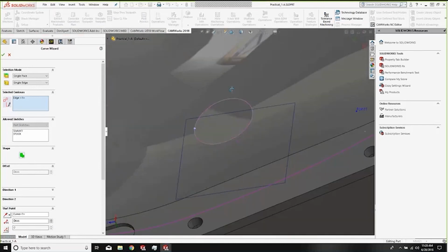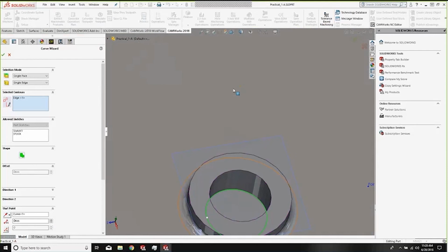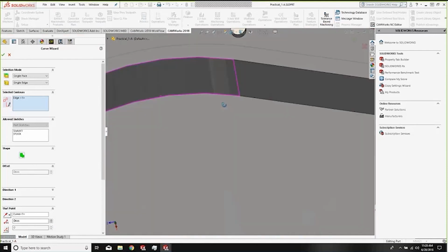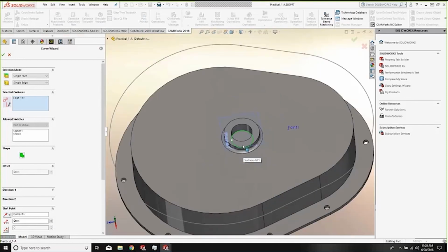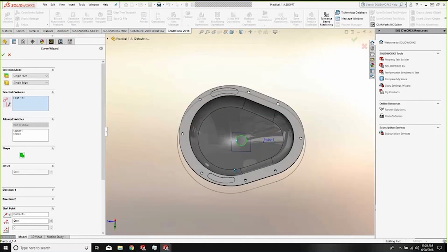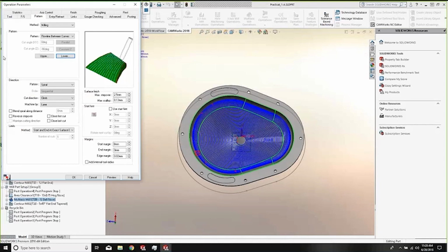This chain right here, which is actually a hole that gets punched through there. Now, the reason I can select that is because I drilled a hole from this side. So there's not going to be any material there. So that sets the boundary. And what those curves dictate is cut direction. I'm going to start top and cut the bottom.